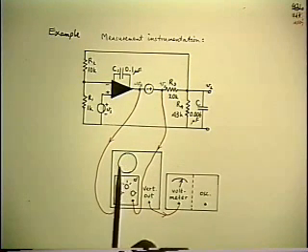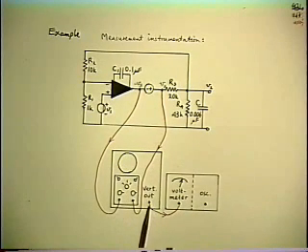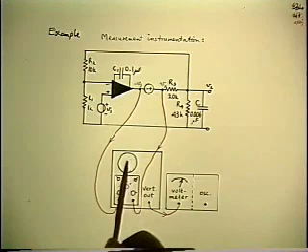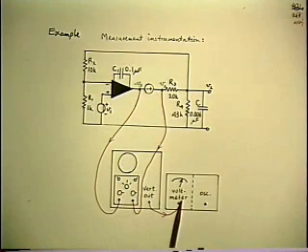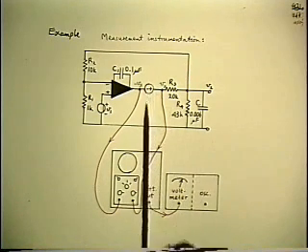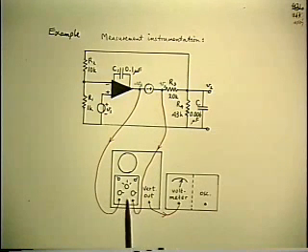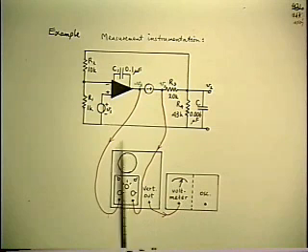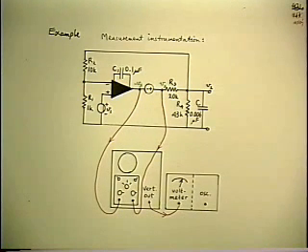And Tektronix also conveniently provides a vertical output, so you not only look at the waveform on the screen, but you plug it into the analyzer, so you measure it also. And of course, to measure the magnitude of the loop gain at any particular frequency, you simply switch from one channel to the other and take the reading in dB and subtract the 2 dBs, and that gives you the magnitude of the ratio. That's straightforward.